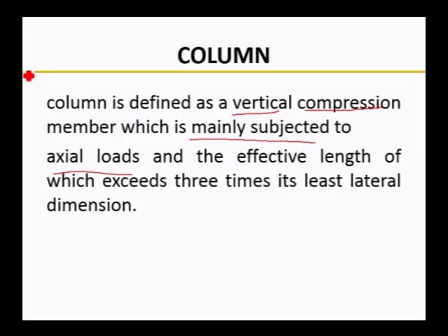A vertical compression member which is mainly subjected to axial loads, and whose effective length exceeds 3 times its least lateral dimension, is called a column. That is what I showed in the previous slide. This is the definition of column.